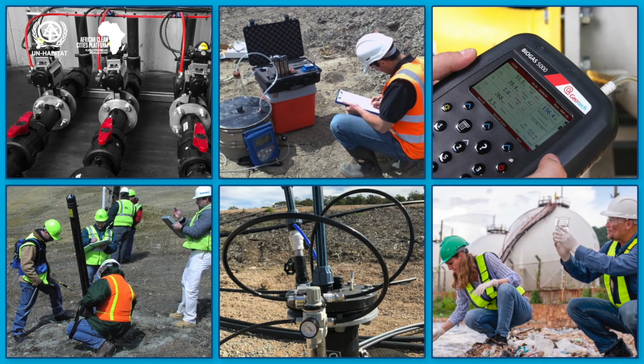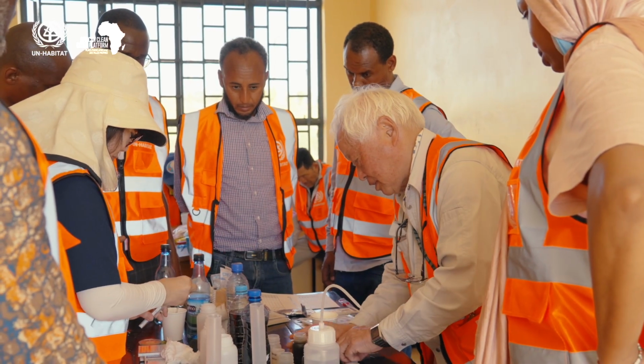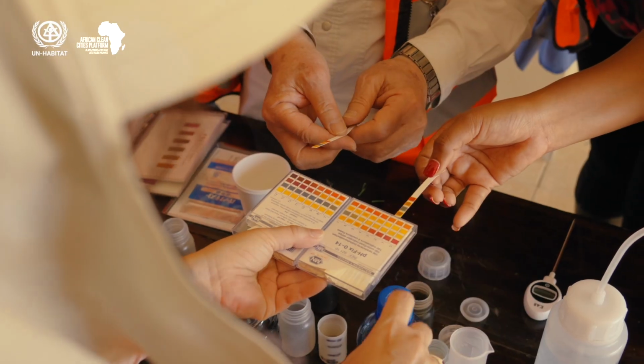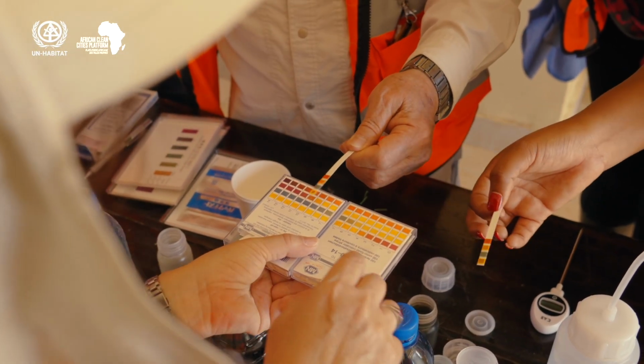A final point on the treatment of leachate is the need for careful monitoring and control. Monitoring sensors at the liner area can be added at the construction phase along with other similar equipment. But the more advanced things are, the higher the capital and operational costs and higher technical management skills are required. However, all that is required initially is for field staff to gradually increase their competency in the monitoring of gas emissions and leachate. This, along with the gradual introduction of technology, can be expanded over time.